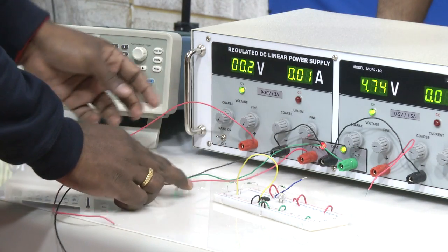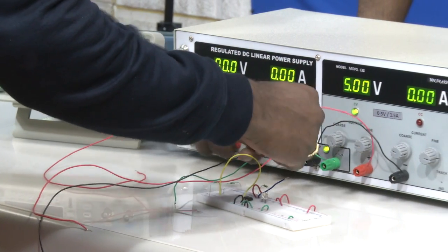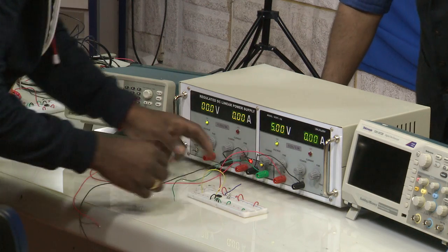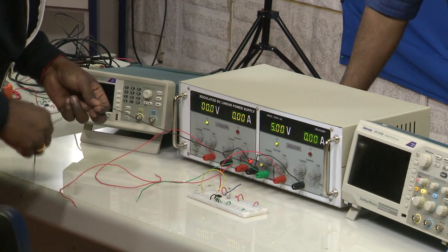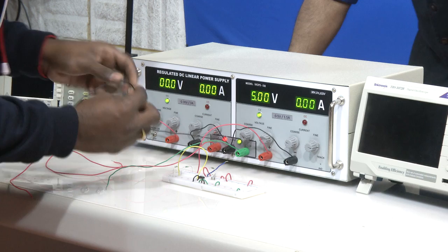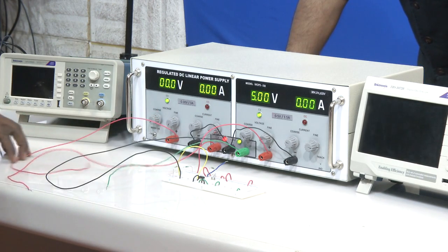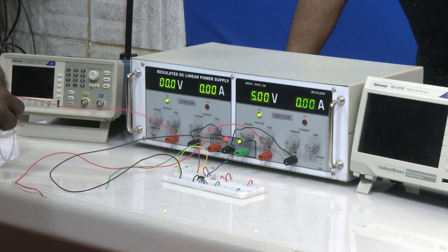We will apply bias voltage across the operational amplifier. So, you all know what is bias voltage, plus 15 minus 15, right. For this particular DC power supply, we already know the center terminals, 3 terminals in the center, red, black and green. Through that we can apply plus 15 and minus 15, alright.